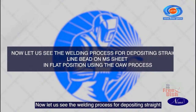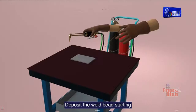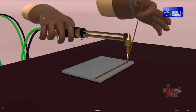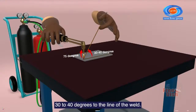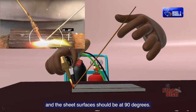Now let us see the welding process for depositing straight line beads on the MS plate in flat position using OAW process. Deposit the weld bead starting from the rightmost point of a punched line and moving left along the line. Hold the blowpipe at 75 degrees and the filler rod at 30 to 40 degrees to the line of the weld. The angle between the blowpipe nozzle and filler rod and the sheet surfaces should be at 90 degrees.